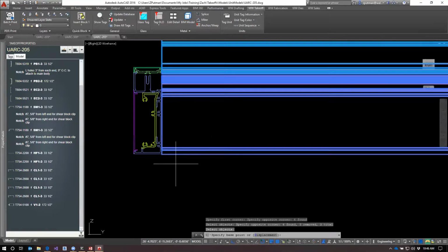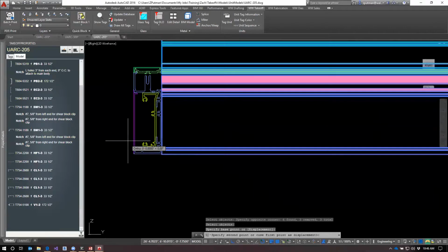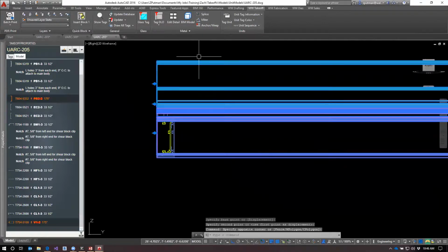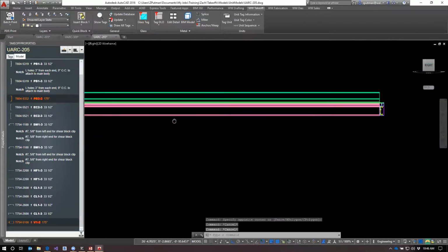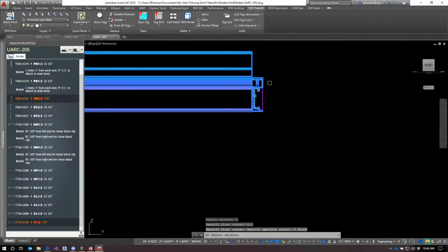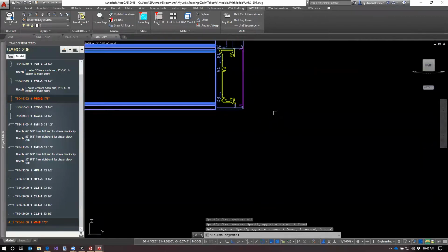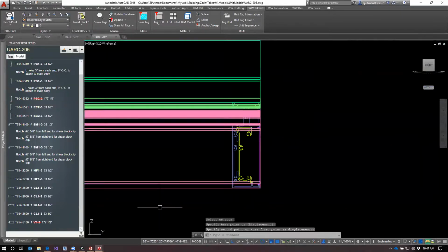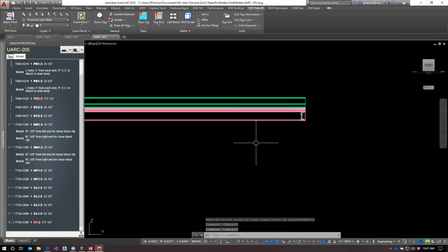That base point here, and nope, stretch does not want to work, or maybe it won't show me visually. Oh, so it did work. It just doesn't show you visually where it's moving to. Let's do the same thing here. Stretch like that. I don't want to move any of those. So pick here. Notice that, again, it doesn't allow you to move the extrusion up and down like it would a line. It just does it that way. Now let's unisolate everything.